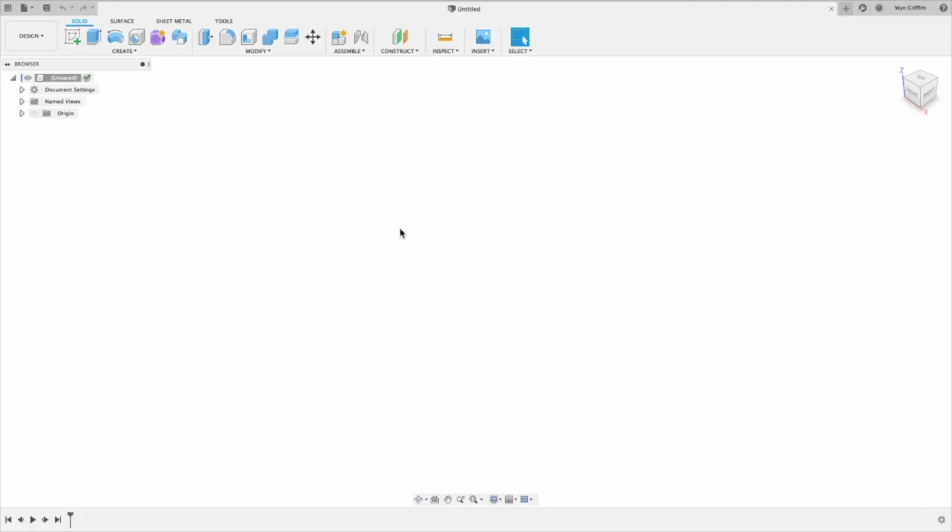What we're looking at here then is our 3D modelling environment. Okay, we can't actually see anything in there, but on the left hand side we have a folder there. If you click on the little eyeball, switch the visibility of that folder on and we can expand the little arrow and we can see what's inside there as well. So we've got an origin, we've got 3 axes, we've got 3 work planes. Okay, so I'm just going to collapse that and hide those again.